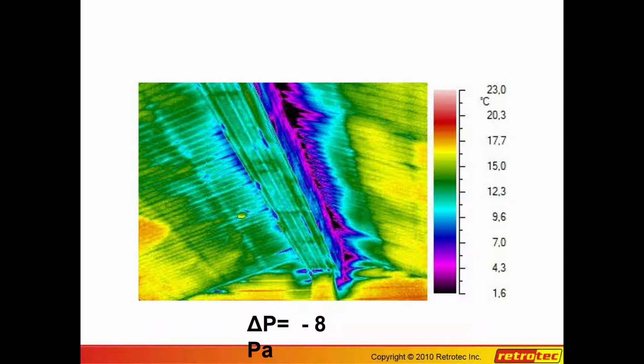Here what we've done is a flow reversal. We've sucked the cold air into the upper leaks, whereas before the warm air was leaking out through the upper leaks, really making them very, very hard to see. So the moment we use the blower door, it supercharges your infrared, and all of the best trainers on the infrared side strongly recommend that you use some kind of depressurization device from inside when using infrared, and a pressurization device blowing air into the building when you're looking at the building from outside.